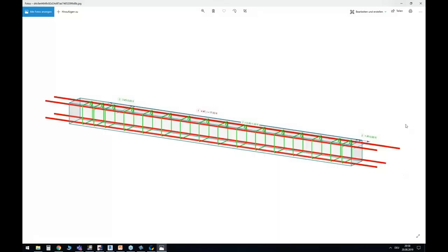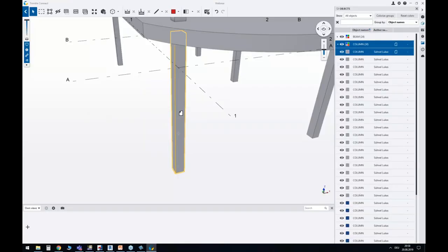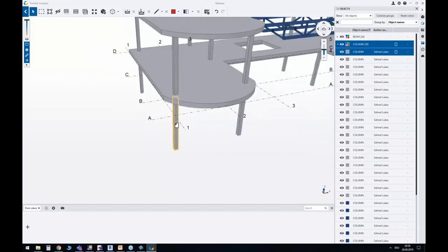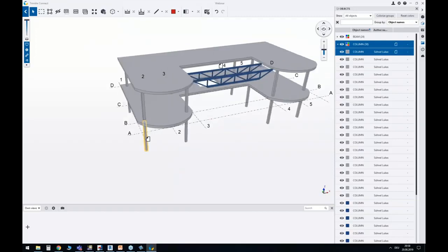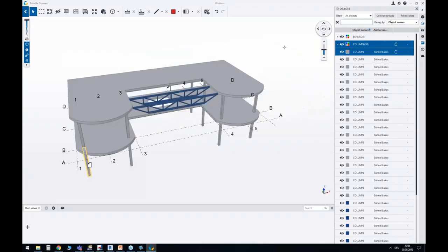Here I designed the required reinforcement in the column, and I linked that graphic also to the IFC object of the column. So Trimble Connect is maybe the tool you would use if you want to document results from RFEM or whatever application together with the Tekla structure.